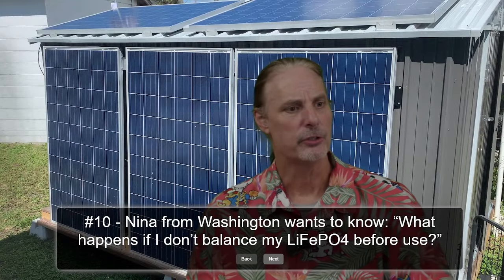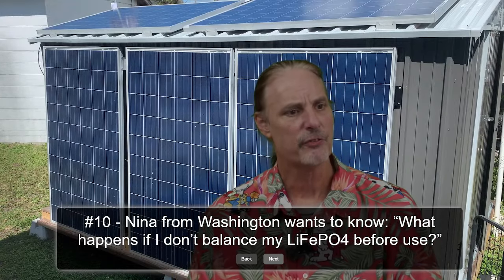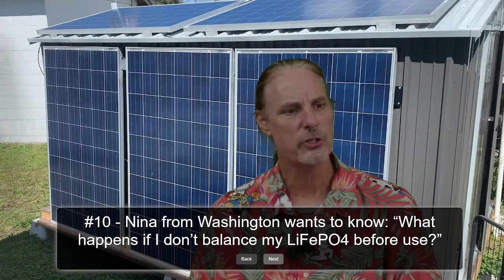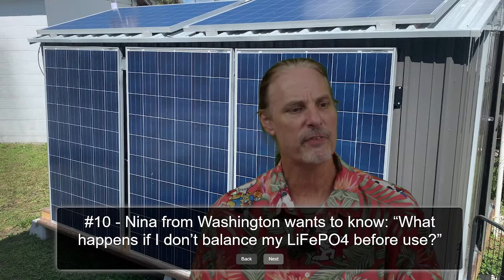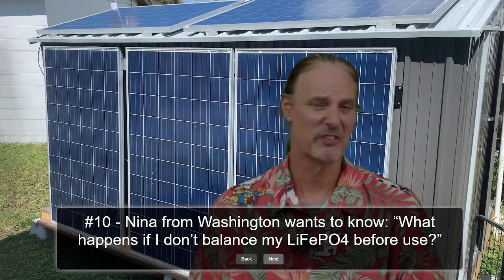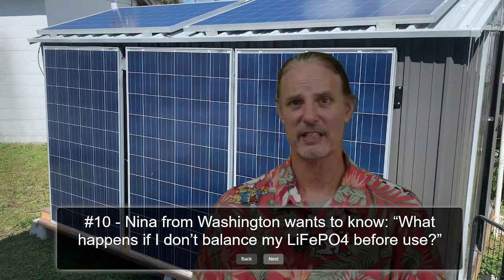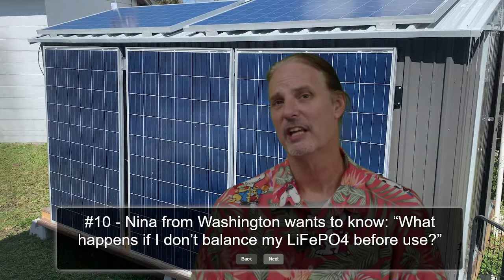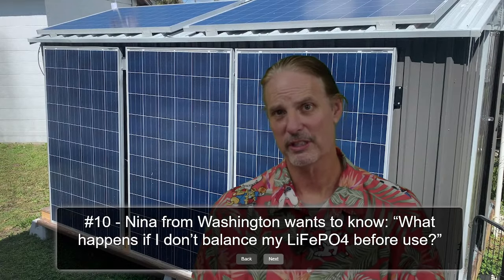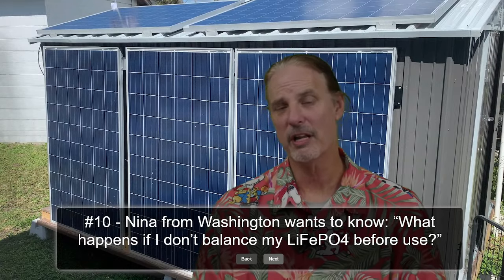Moving on to Nina. Nina from Washington wants to know, what happens if I don't balance my LiFePO4 battery before use? In most cases, if it's a purchased battery, it will be balanced enough that as long as you top balance it with the solar system, the inverter or whatnot, and leave it ample time to get there, it will balance itself and it'll take care of it.